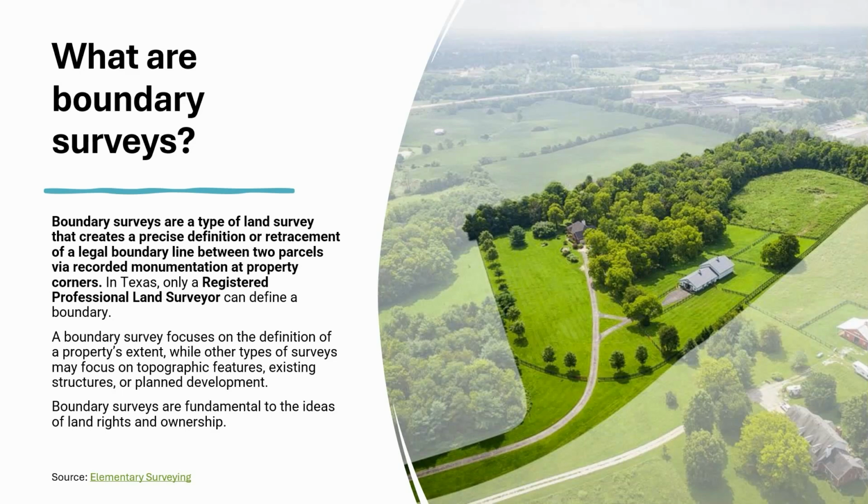So the extent of some topo survey that you did maybe doesn't require a boundary if it doesn't need to be represented, because the data is more relative, as well as interpolated. We create that continuous surface through a series of individual points to try to say what a continuous surface looks like. So it's a representation, not the same thing as a boundary, which is a clear, hard definition.